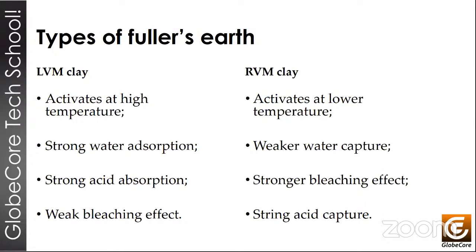So I don't think that using Fuller's Earth to absorb moisture is a good idea, because there are more economical and simpler processes for that purpose. That includes thermal vacuum to remove moisture. In addition, the thermal vacuum process doesn't really involve consumables, unlike Fuller's Earth. For Fuller's Earth, there comes a moment when its properties are finally depleted or exhausted, and it needs to be disposed of. And of course, this must be done in a safe manner, because saturated Fuller's Earth is a hazardous waste, and its disposal entails significant costs.